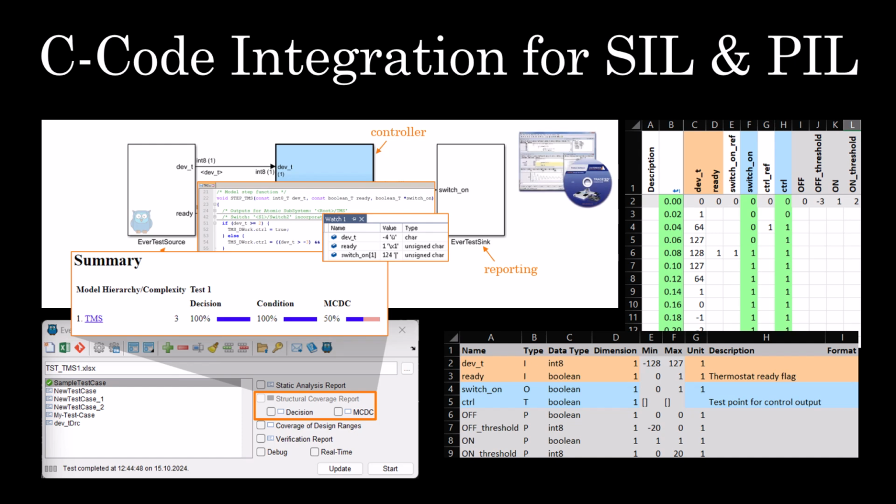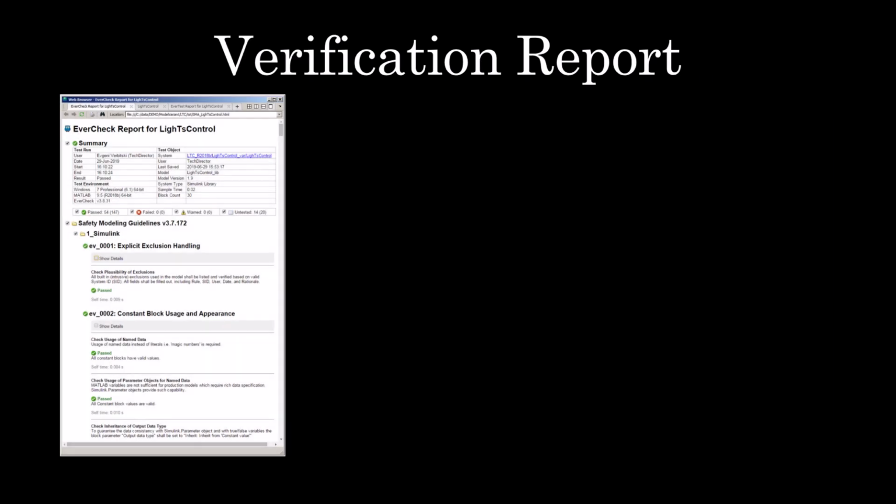You may also decide to run the processor-in-the-loop simulation with Lauterbach Trace 32 simulator, or you may also run the hard processor-in-the-loop simulation with the appropriate developing board and the hardware debugger. C sources can be used and tested with existing test cases in different environments by using native compilers, profilers, and debuggers. The verification reports are generated as single HTML files.